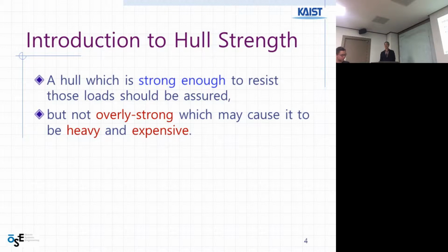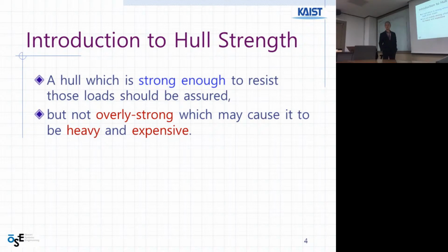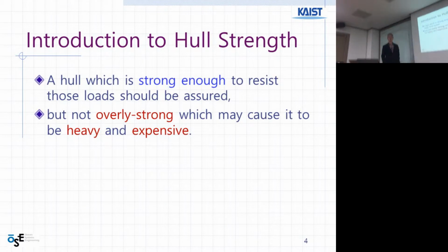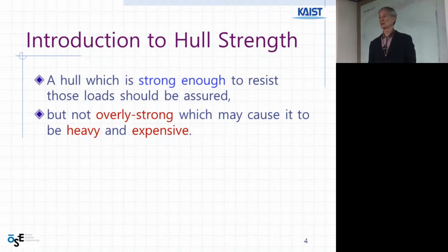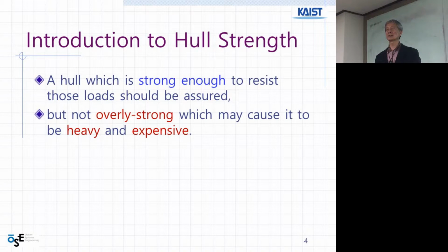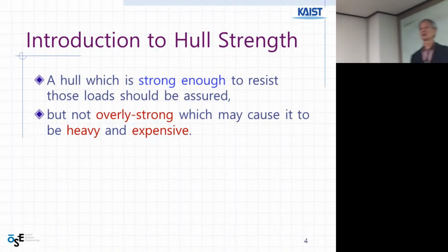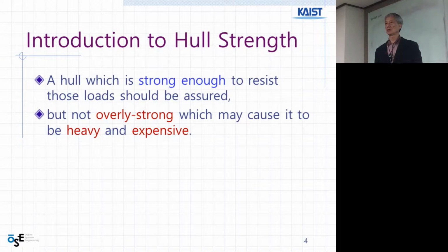Hull form. Hull form is used for hydrodynamics. So we need to have strength, because of the load coming from the ocean. The biggest one is hydrostatic load coming from weight and buoyancy: the unbalance between weight distribution and buoyancy distribution along the ship surface.